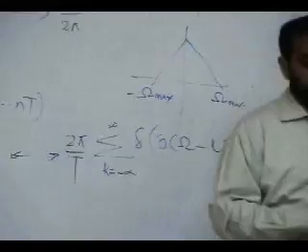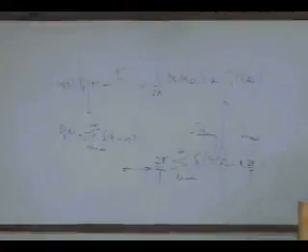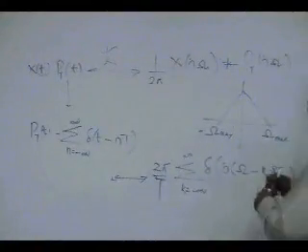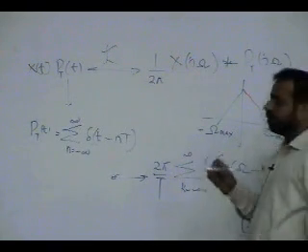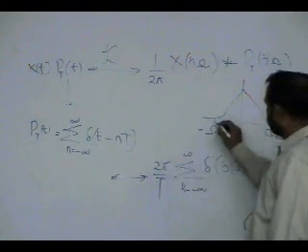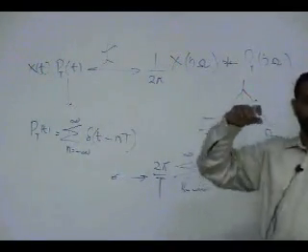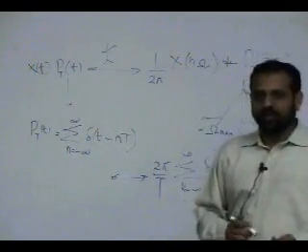So this is the Fourier transform of a band limited signal. In reality, all signals are usually time unlimited, and when a signal is time unlimited, it means it is not band limited. But what really happens is that we say it is, let's say, minus 100 dB down.